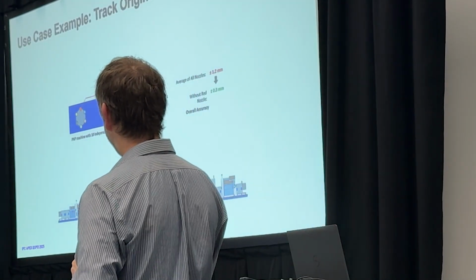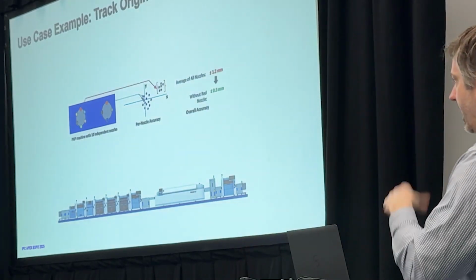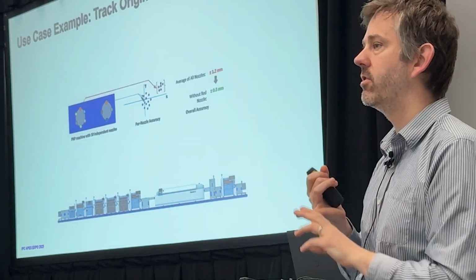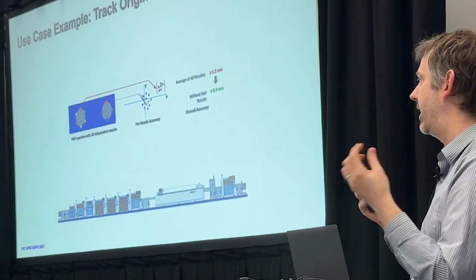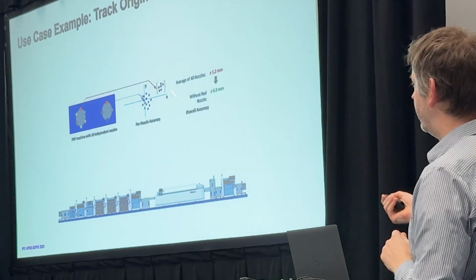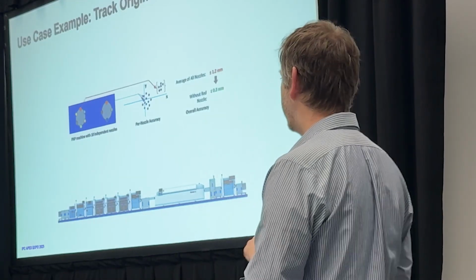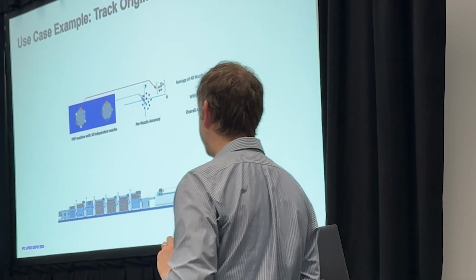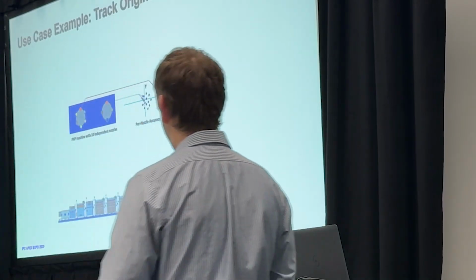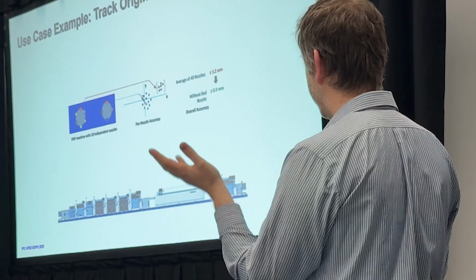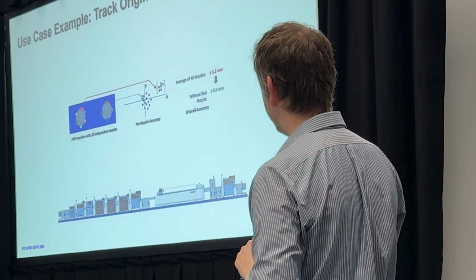So if you take information from the pick and place, you put it together, and now you take all of the defects that you found at AOI and you annotate them with what nozzle was used for that exact placement, which is something that's known from the pick and place's program. You could pull that off in a file and you could annotate it. You sort of see things like this, where, hey, I've got a problem with one of my nozzles, it's a little bit worn, or maybe I've got a problem with my camera, it's a little bit off in its calibration. And you identify, actually, the accuracy of my placements, if I look at everything, was maybe plus or minus a millimeter, but actually that's just because of one bad nozzle.